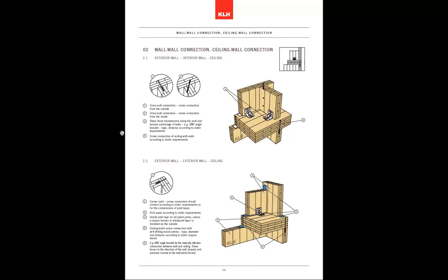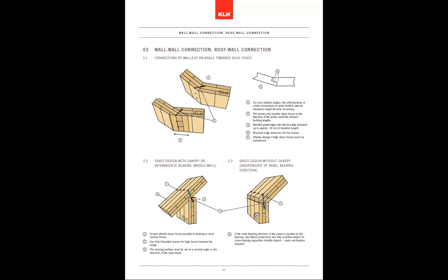Really fantastic. So there are some corner details, wall to wall, and these are the steel fixing cleats. If you really don't want to see those, then your engineer can design those so that they're hidden and integrated into the timber panel. But normally, like here, it doesn't matter because you're going to be laying a floor on top of that to hide it. But certainly you can design those out.